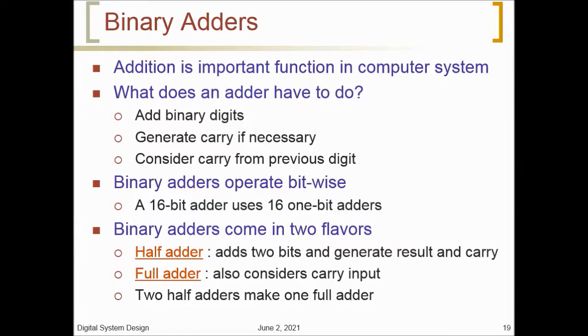A binary adder-subtractor is a combinational circuit that performs the arithmetic operations of addition and subtraction with binary numbers. To develop this circuit by means of hierarchical design, the half adder design is carried out first, from which we develop the full adder.